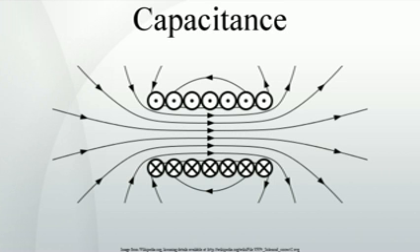Stray capacitance is often encountered in amplifier circuits in the form of feedback capacitance that interconnects the input and output nodes, both defined relative to a common ground. It is often convenient for analytical purposes to replace this capacitance with a combination of one input-to-ground capacitance and one output-to-ground capacitance. The original configuration, including the input-to-output capacitance, is often referred to as a pi configuration. Miller's theorem can be used to effect this replacement.